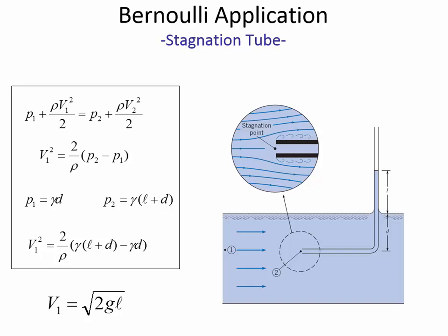So will there really be energy losses? You see how they're zooming in on this picture here? It's showing some turbulence, these little vortices and eddies around the side of the object. We could get better results if we make this very thin, or if we have a shape so that there's less of this disturbance. Because what we want is we want the stagnation point to stop perfectly, and then the streamline right next to it just slips past without any sort of turbulence or disturbance. And so, how much error we have in measuring the velocity this way depends on the shape of the tube.